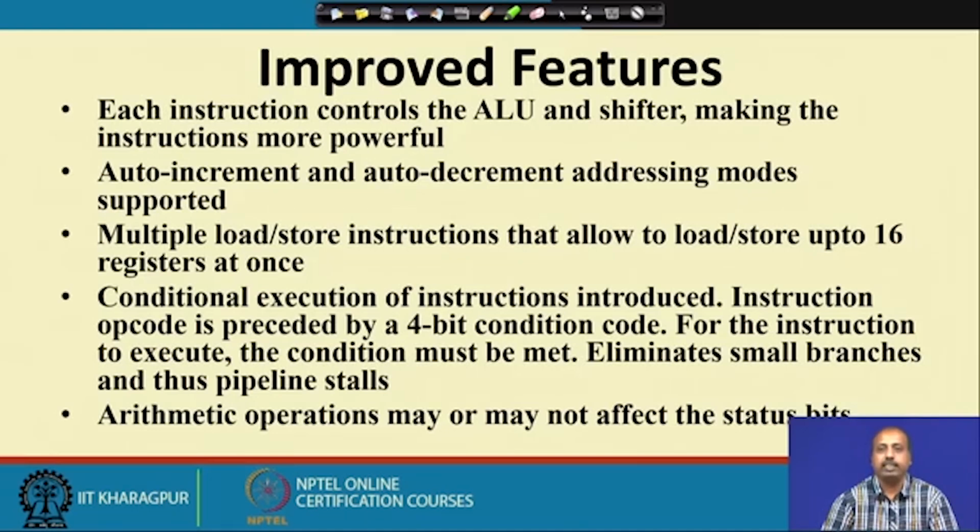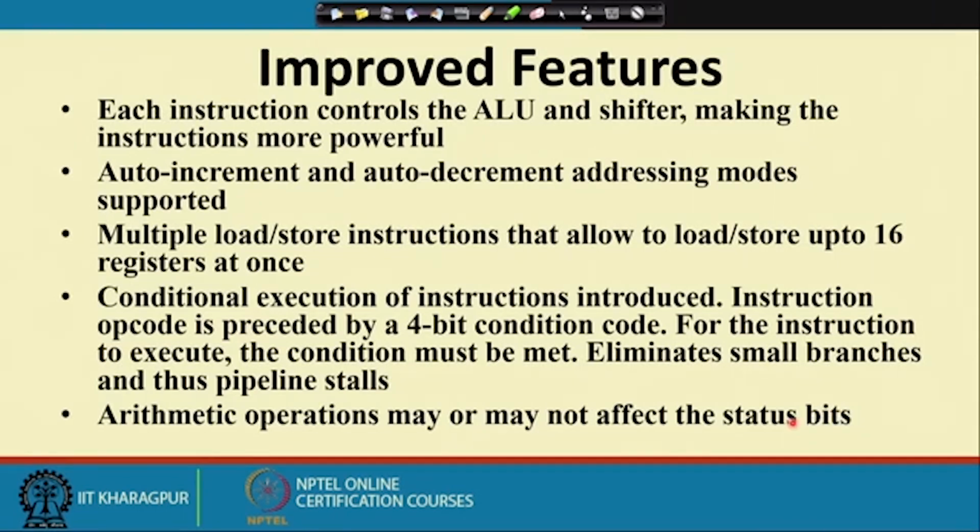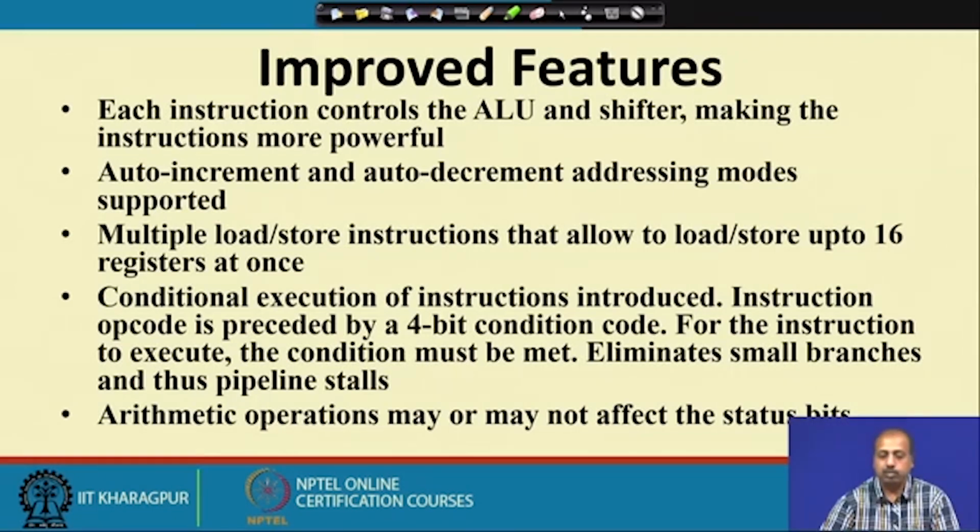The add instruction has two variants, as we will see later. One is add, which will not affect the status flags, and another variant is add S, which will affect the status flags. And this is useful because of conditional branching.